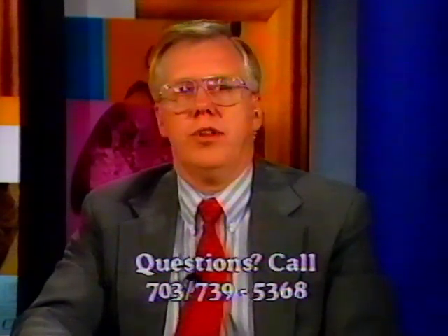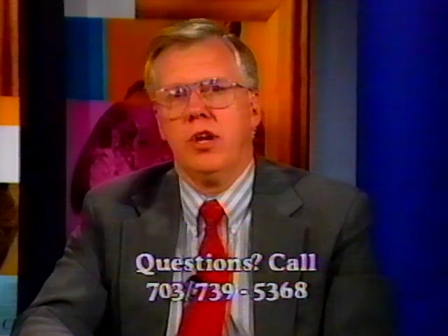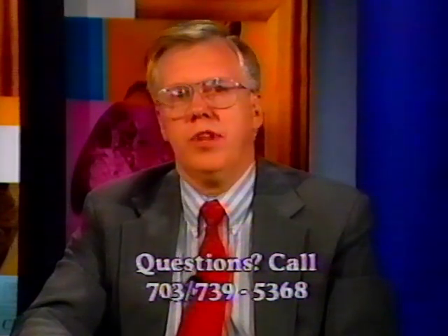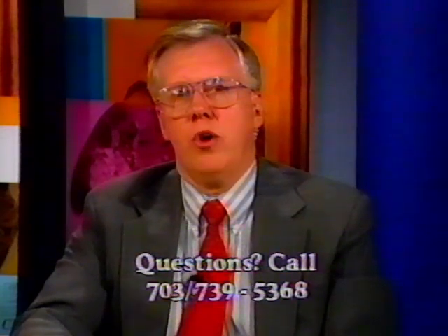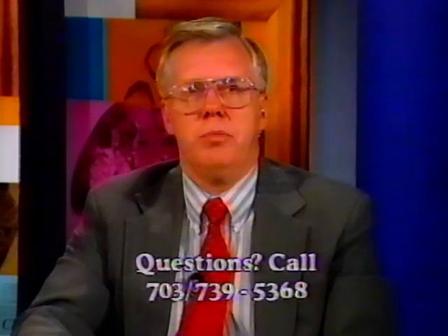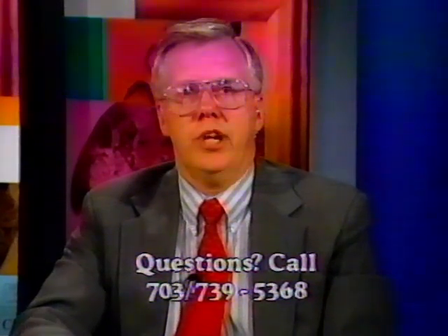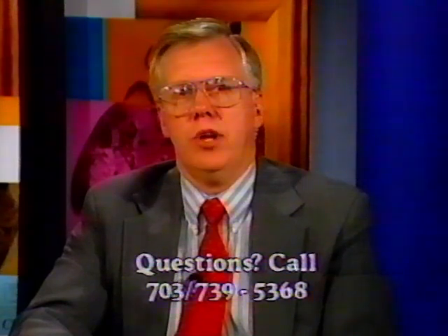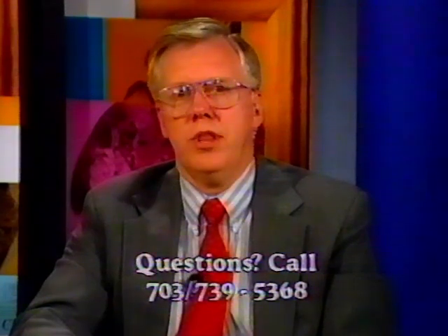And just a reminder that the other thing that's happening when it's doing that, that's the only frequency that you'll ever have to load in the IRD. All of the other channel information will be transmitted to your IRD on that home channel. The home channel we have you tuning to is simply that big MCPC that we're putting up there. But the map that you will be downloading, the virtual channel table number 15, includes the frequency, the polarization, all the information you need to tune to the SCPC feeds and the analog feeds that are included within that map.